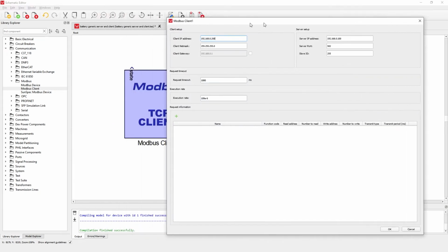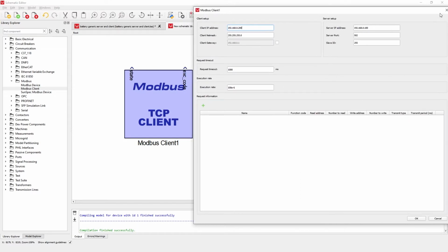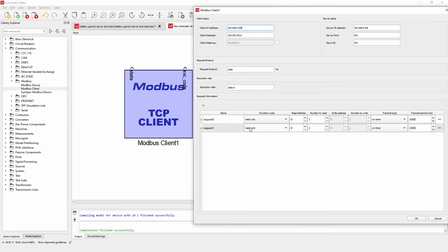The Modbus client component available with version 2021.3 of HIL Control Center only supports 16-bit registers. However, 32-bit and 64-bit registers are planned for subsequent releases. You can find more information about this component and how it is implemented in the HIL Documentation Hub.